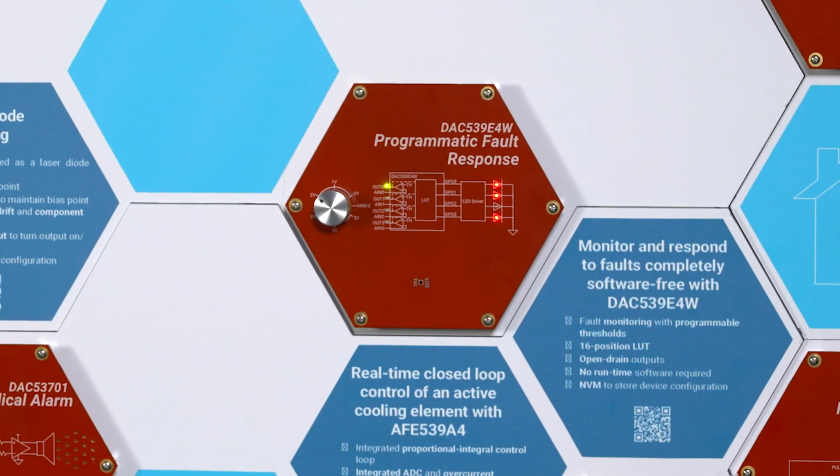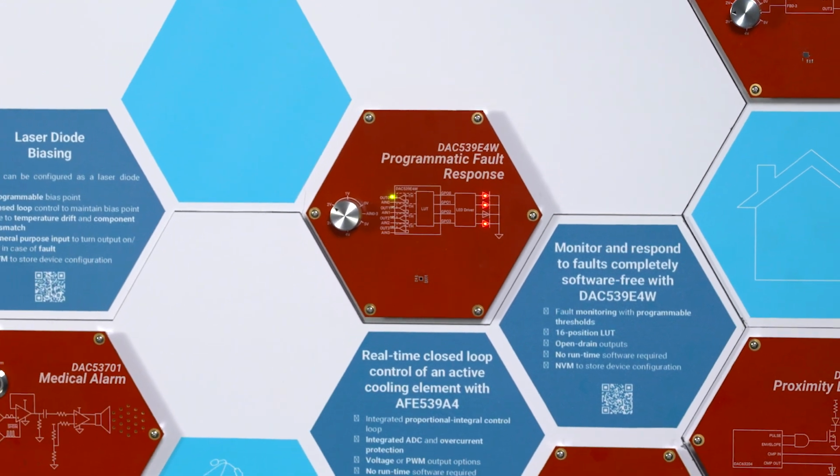The discrete component approach for safety monitoring, while simpler and often lower cost, lacks intelligence and consumes a large board area. Meanwhile, an MCU-based approach adds flexibility and intelligence, but the cost of software development, runtime maintenance, and certification makes it more expensive.